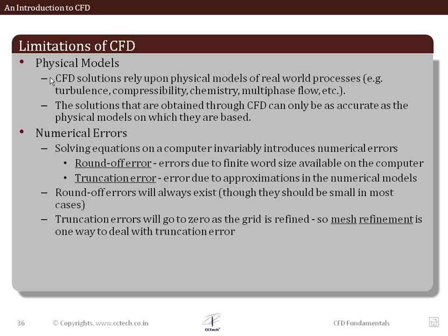Sometimes we also have modeling errors because of wrong boundary conditions, which you would come across when we deal more in a profound way with the software Fluent. The boundary conditions are often the ones which give a unique solution to the problem inside your computational domain. So if the model is not well defined as far as the boundary conditions are concerned, you're bound to have errors in that case also.